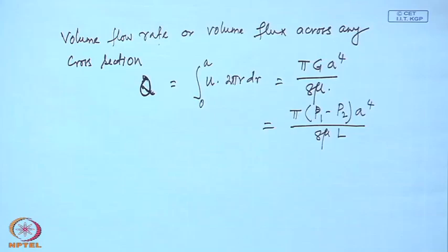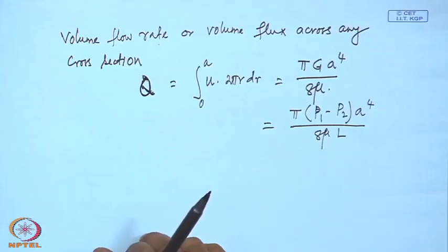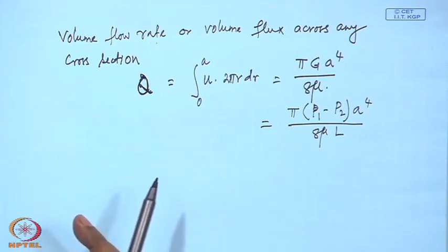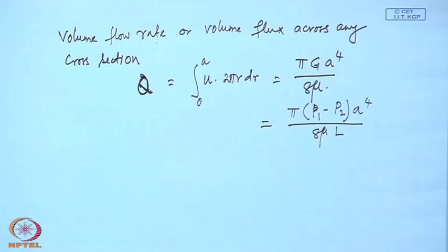As an example, if you are considering a pipe which is inclined, you should take the effect of gravitational force also within that modified pressure. Do not forget that this pressure itself contains the gravitational effect, or the body force effect. You are not writing them separately, but that body force is present within this pressure itself. So, this is not simply the fluid static pressure plus the effect of body force; that is also within the pressure.